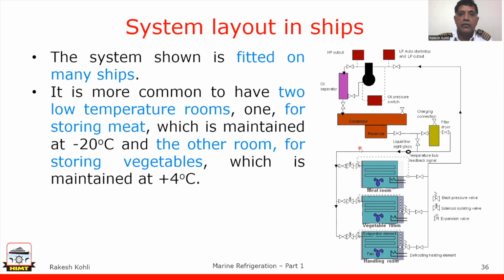It has a compressor, which is shown here, then a condenser, shown here, then a place where the gas expands and comes down to a lower temperature, the expansion valve, shown as this, and the evaporator, where the heat exchange happens, or the fridge room.